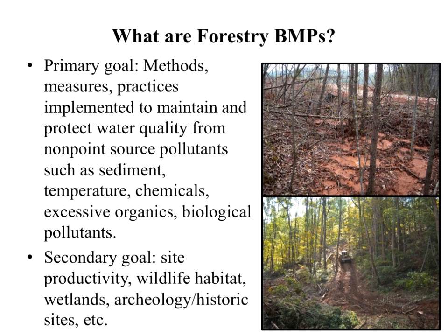I hope all of y'all can see the sediment that is being trapped by it in this particular instance. Another example of where we use BMPs in many instances would be on roads and skid trails. If you take a look at the lower slide there, you can see a skidder coming down a very long skid trail. It was about an 800-foot long skid trail on about a 35% slope. Desperately in need of some water control structures and some closure measures once they're done with this.